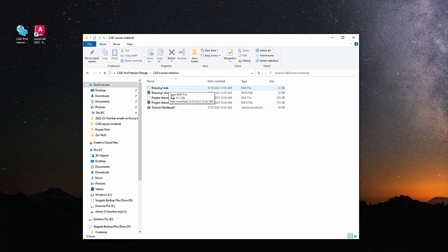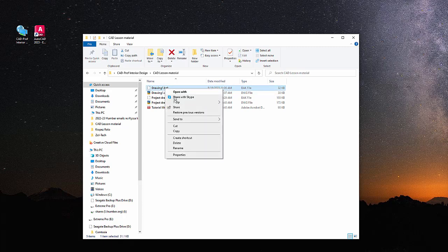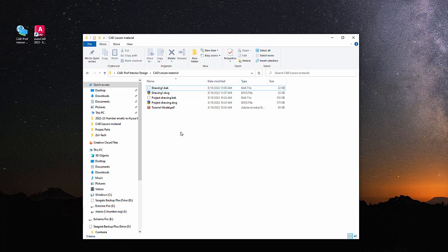If I ever get a corrupt drawing file, I can restore the backup file just by changing these last 3 letters. And all we do is right click on it. In this particular case, you can select rename, and you can see how I can change those last 3 letters. I can't do that here right now because the drawings have the same name. But if I do that, that is the previous saved version. So that's a great way of always being able to have a dual copy of your work and therefore be able to save your work.